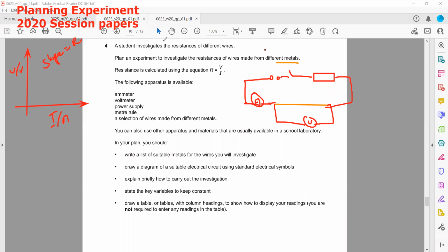But if we did the opposite, if we plot current on the y-axis, normally we draw current on the y-axis, as I mentioned, because the independent variable is on the x-axis. So voltage is independent and current depends on voltage. So with voltage on the x-axis and current on the y-axis, the slope of this line represents the reciprocal of resistance.